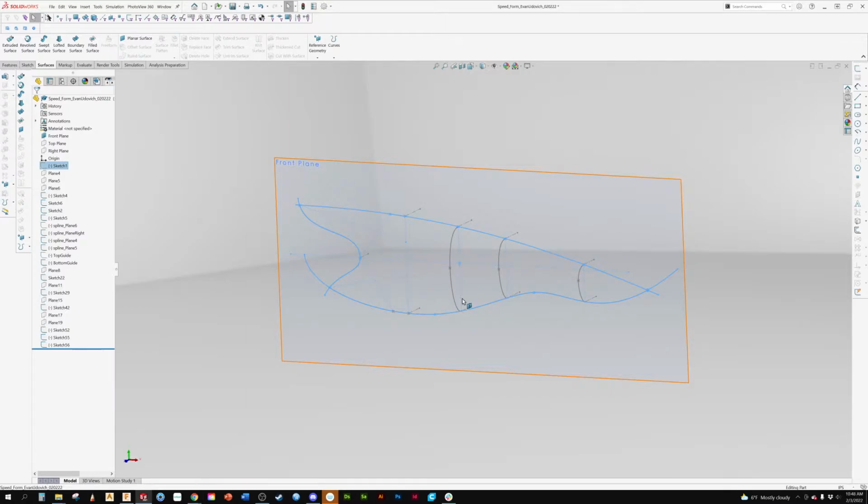Many times what we want to do is just use this as a reference and rebuild the sketches. And the reason for that is if we turn it on where you have multiple curves that overlap the sketch, there's a chance that you might grab the wrong curve or the wrong edge.